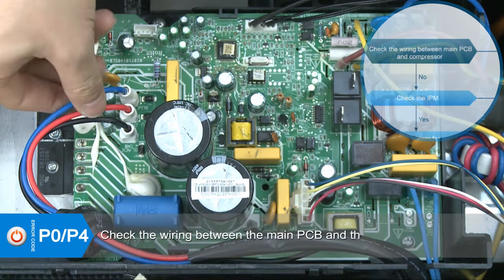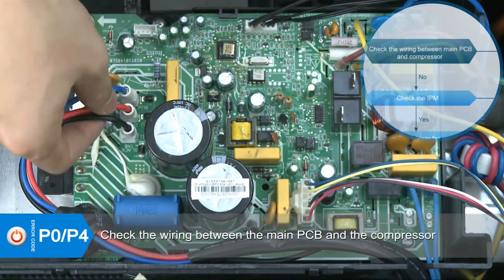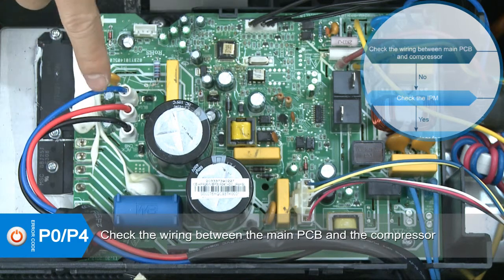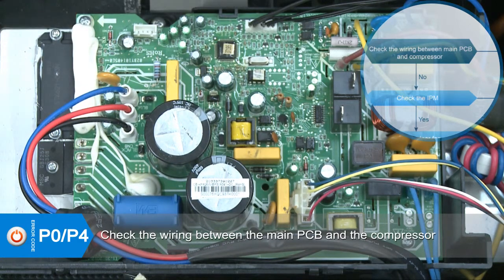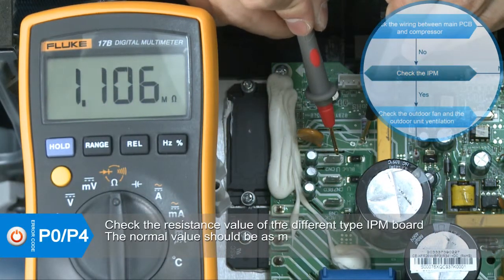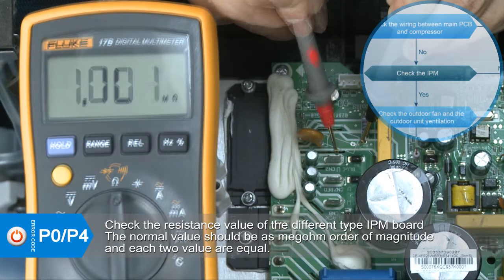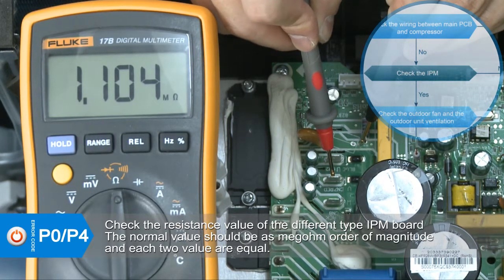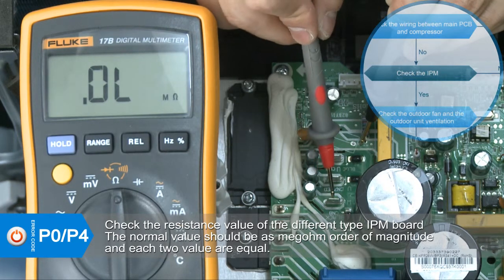Check the wiring between the main PCB and the compressor. If the wiring is correct, check if IPM is operating well. Check the resistance value between P and U, V, W. The normal value should be of megohm order of magnitude, and each two values are equal.